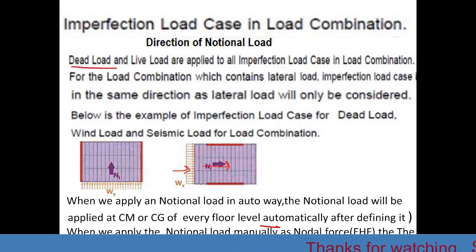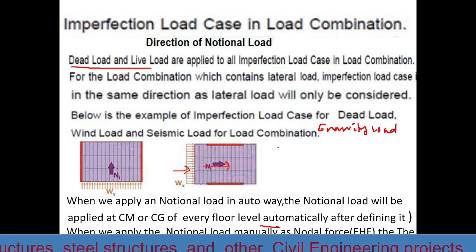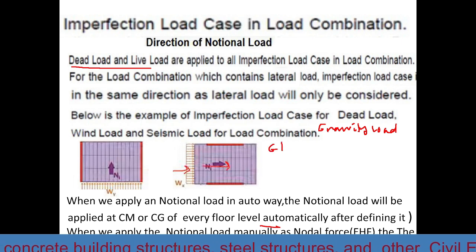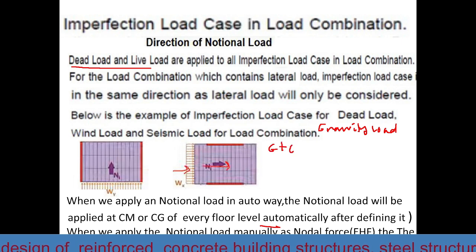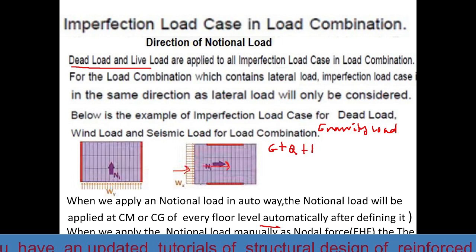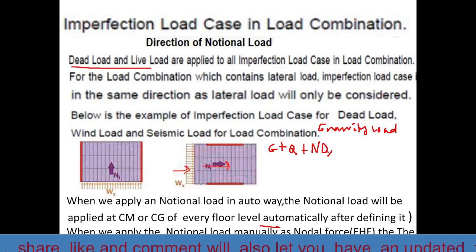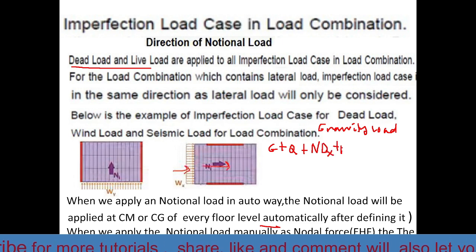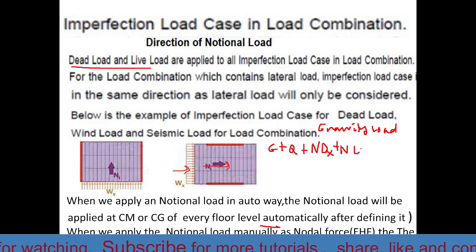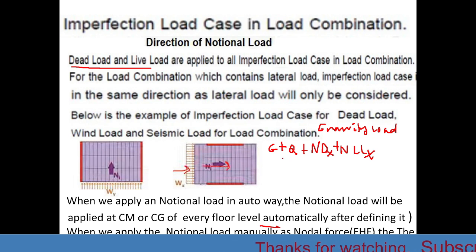For the gravity load combination, that is the dead load plus the live load plus notional dead load x plus notional live load x.